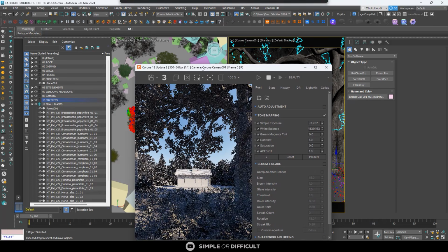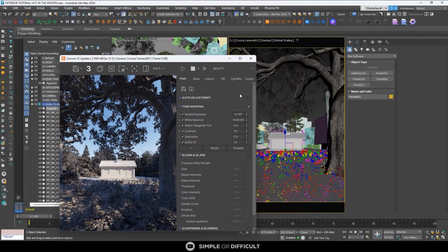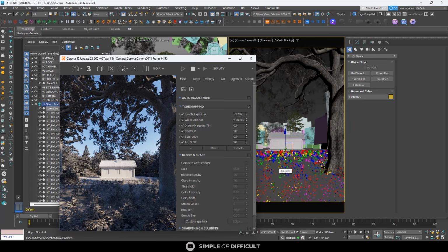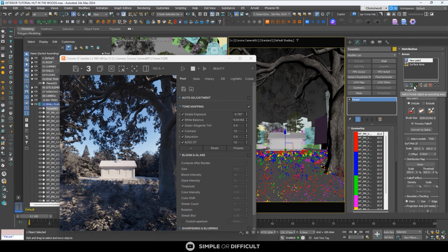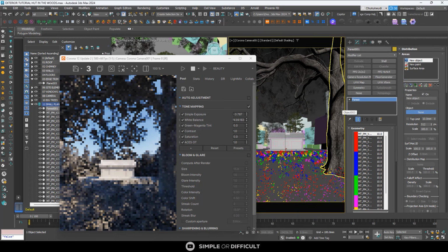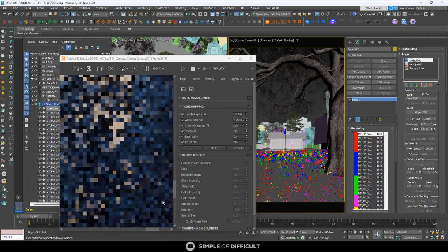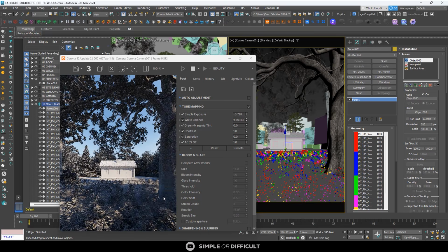And then come over here. Select this forest. If we use this entire tree to do this, the place where we have the leaves is going to be part of what will be excluded. And that's not what we want. We just want this tree trunk area to be excluded. So with this selected, I'm going to come over here, right? And I'm going to click on this part, and then click this tree trunk. Okay, it is just going to exclude the area around that tree trunk, so that there will be no plant growing on it.